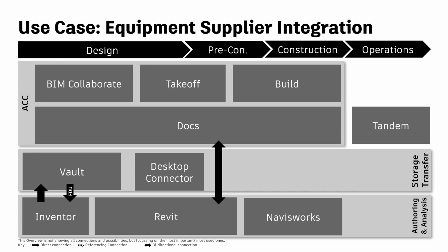We could of course continue the Inventor data without simplification, but there really is no point in doing so, as we only need to be able to see equipment in context of the total factory design. Imagine one type of equipment reoccurs several times within the factory and all the nuts and bolts within the machine have been exposed. This would make the aggregated model top-heavy without serving any purpose. From an integration point of view, we only need a correct envelope representation with the relevant technical connectors exposed.